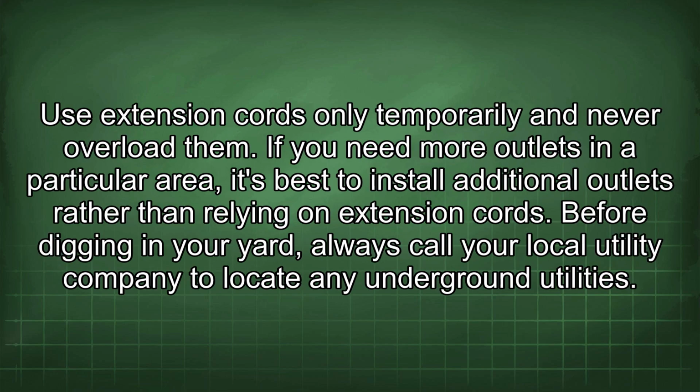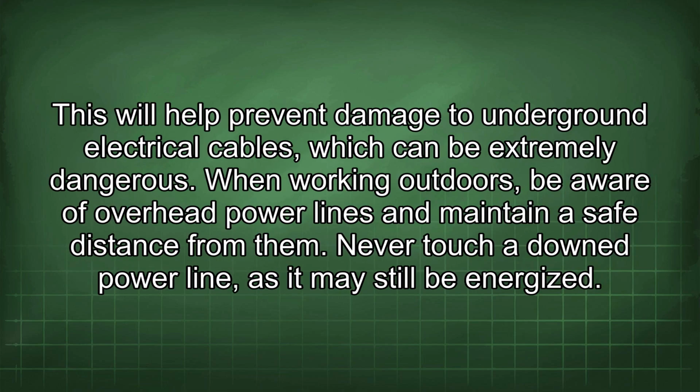Use extension cords only temporarily and never overload them. If you need more outlets in a particular area, it's best to install additional outlets rather than relying on extension cords. Before digging in your yard, always call your local utility company to locate any underground utilities. This will help prevent damage to underground electrical cables, which can be extremely dangerous.